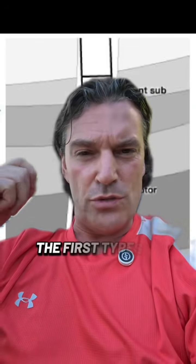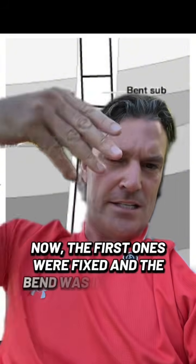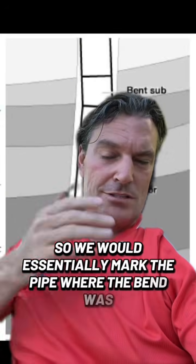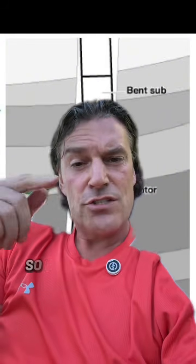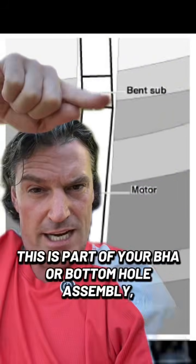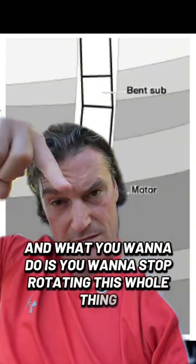The first types of tools that we used were called bend housing motors. Now, the first ones were fixed and the bend was in a certain direction. So we would essentially mark the pipe where the bend was and then at surface align that in the direction we wanted to go, and it would assume that it's going in that direction. So essentially you have your pipe here and there's a bend right there and then it goes in this direction. What you want to do is stop rotating this whole thing.